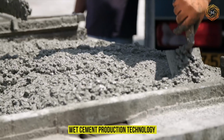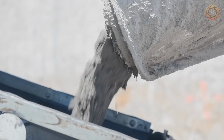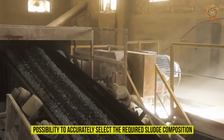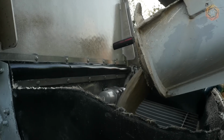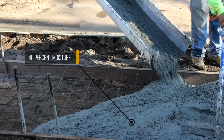Wet cement production technology. What is the advantage of this method of making cement, you may ask? Firstly, it is the possibility to accurately select the required sludge composition, despite the heterogeneity of raw materials. Sludge in this method acquires a liquid consistency, and it contains about 40% moisture.